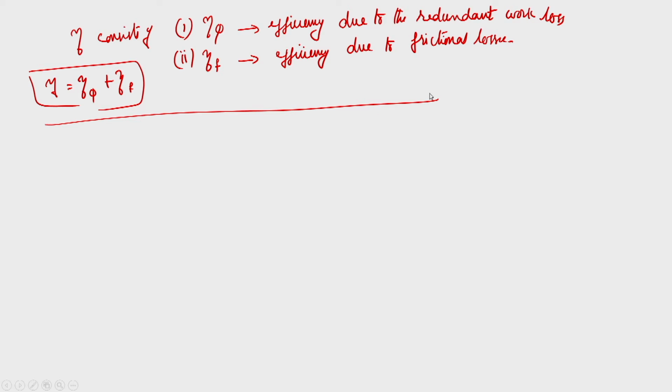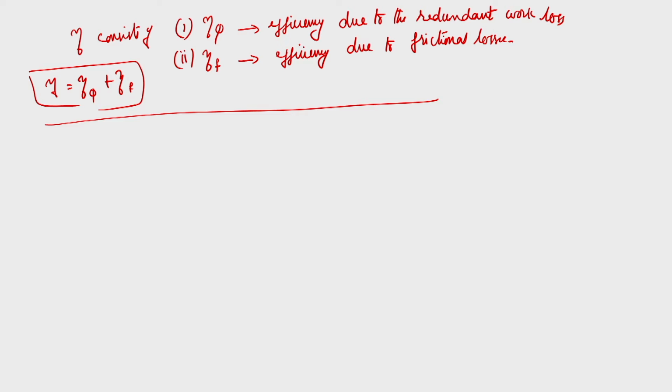So, if you look at this as a basic, this is the simplest form of representation of drawing, provided we know the efficiency factor, or if you know that beta value. Any of these, if you know, you can find out the stress, because in the expression the stress necessary for homogeneous deformation is there. Other things are based on this, you are multiplying with the efficiency factor. Okay. So now let us look at the drawing stress involving friction and redundant work.